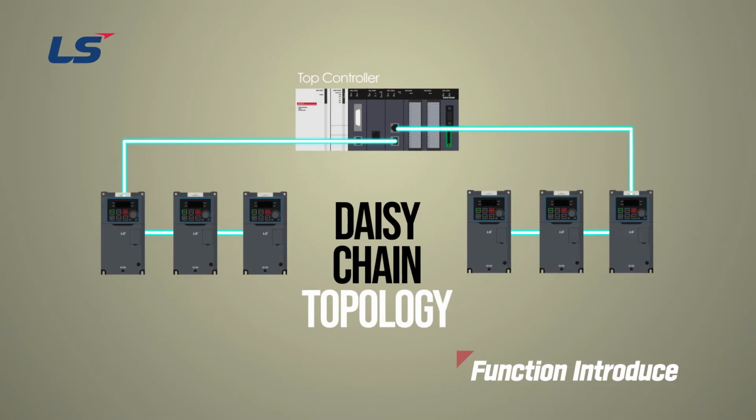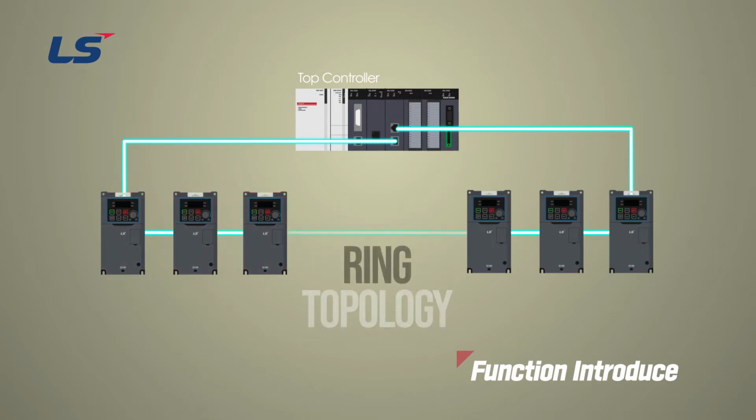RAPIEnet communication can improve network reliability through ring configuration. A typical daisy chain system configuration used in the field is shown in the figure. During data communication, if an error occurs in one module, as shown below, or an error occurs due to a problem such as cable disconnection, communication between the modules at the next point and the master becomes impossible. Such network vulnerabilities can be easily maintained when problems occur in the network through RAPIEnet's ring topology network configuration.